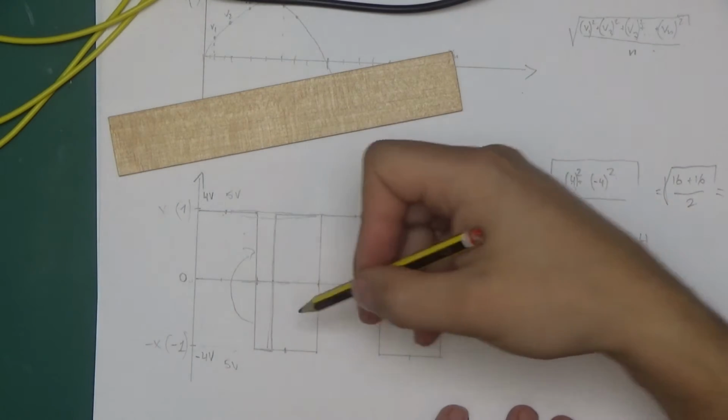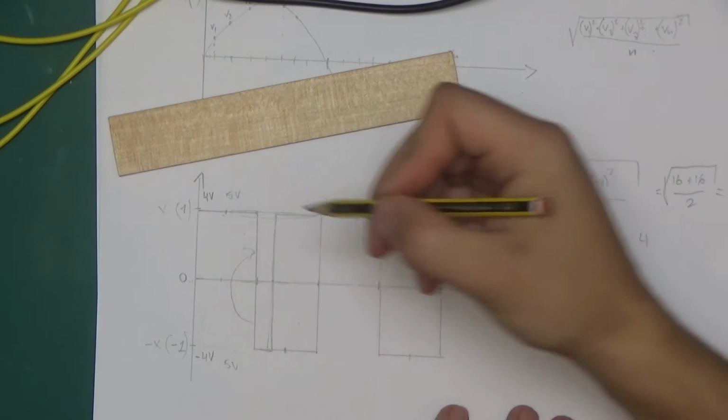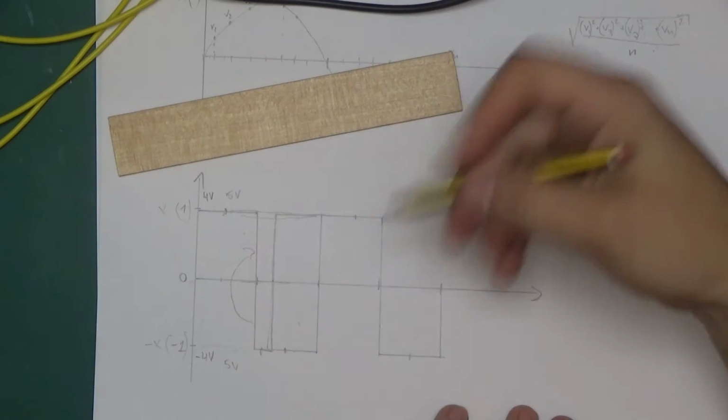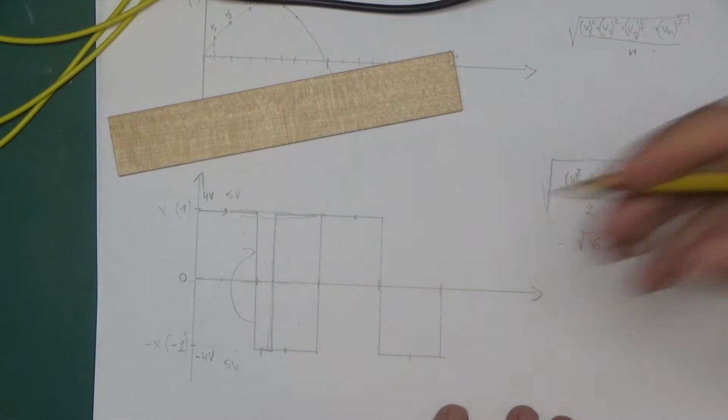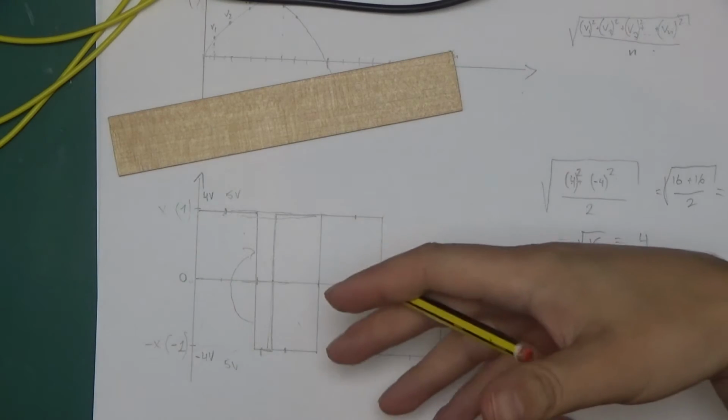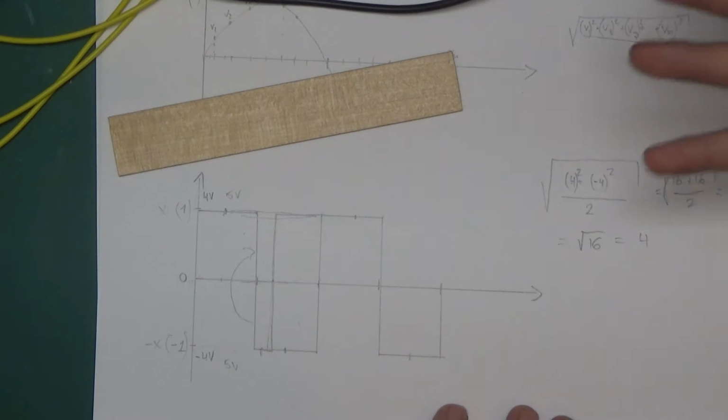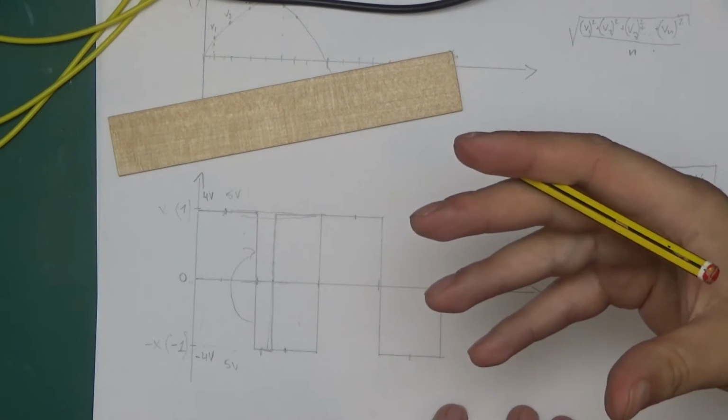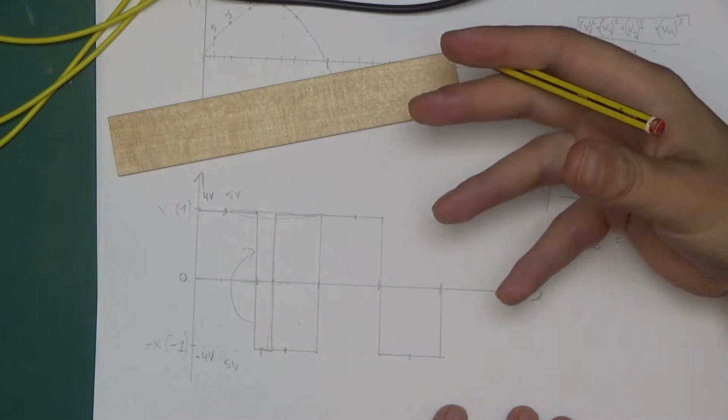For measuring a signal like this, again, we only need 2 measurements. Because it's a square wave, you take the positive peak value, negative peak value, square them, add them up together, divide by 2, and take a square root out of it. That is the true RMS value of a square wave signal.